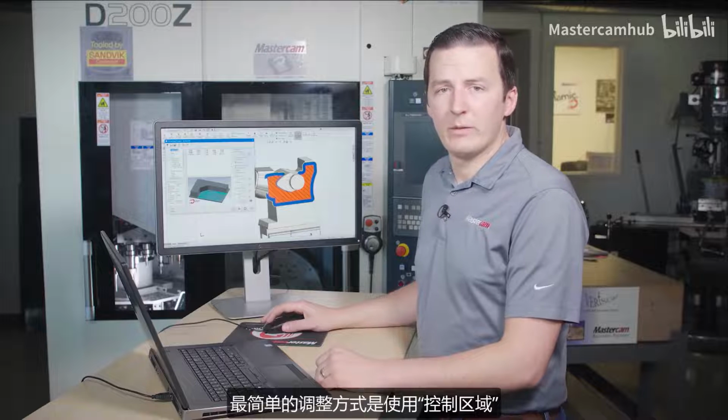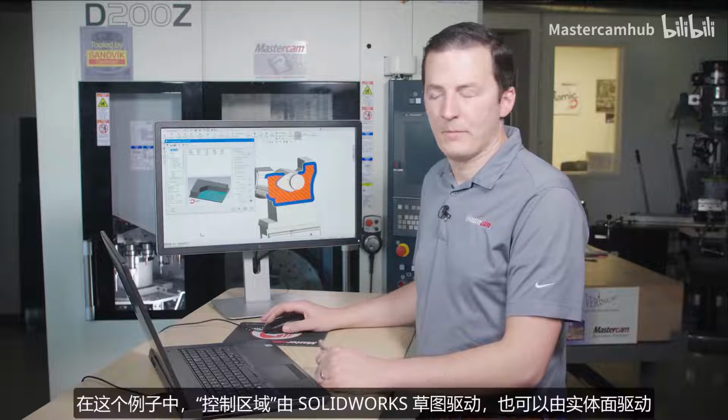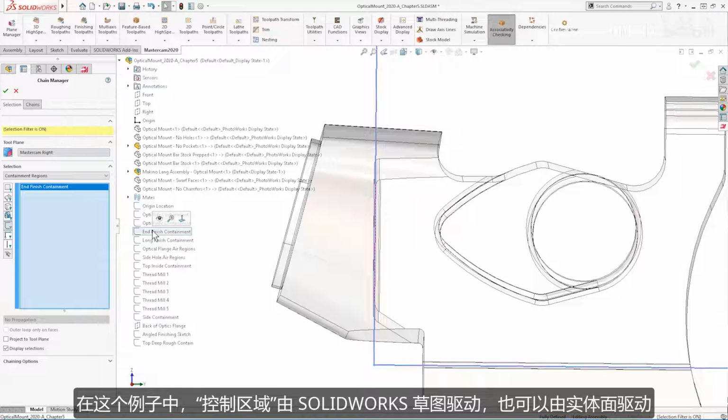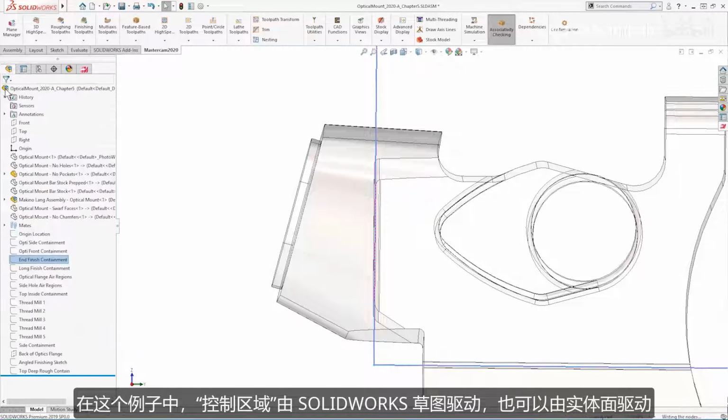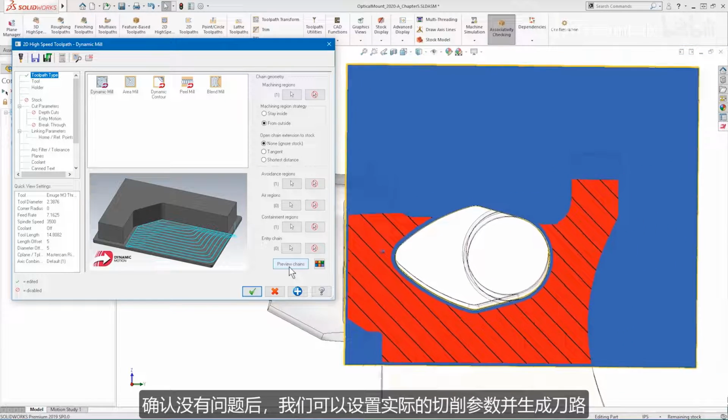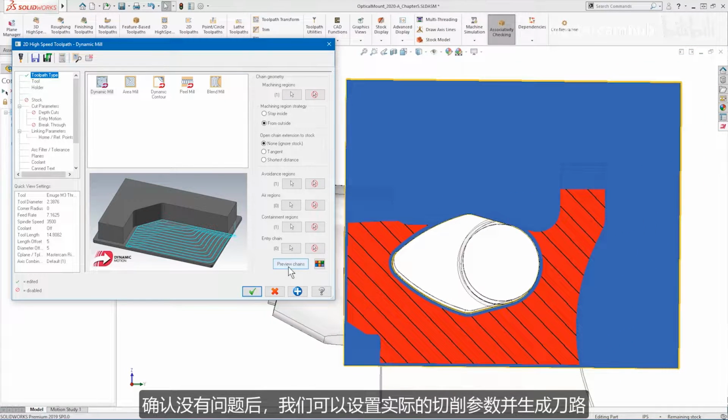The easiest way to correct this behavior is with a containment boundary. In this example, the containment boundary is driven by a SolidWorks sketch, but it can also be driven by solid faces. Another check of the region chaining preview should show an improved boundary. When satisfied with the preview, we can set up our actual cut parameters and generate the toolpath.